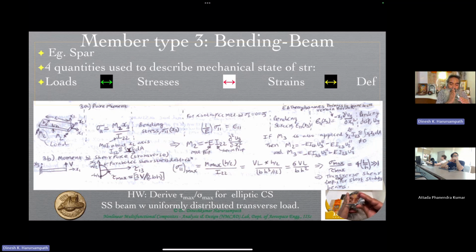That force is going to create a moment, but a shear force is also required in order to resist it, because at any cross section there's not only pure bending but also a shear force coming from that. So with both put together, you don't call that problem pure bending anymore. You just call it a bending problem.